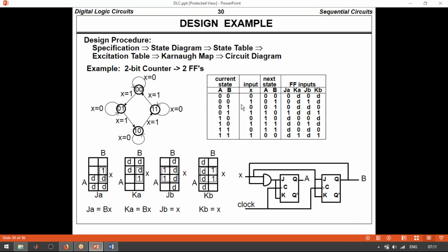So here, do you know the excitation table? No. Okay. So excitation table, in the sense, truth table you know. Normally, truth table means based on the input, what output will come. So that's actually a truth table. And in case of excitation table, from the state or output, we are defining the input.